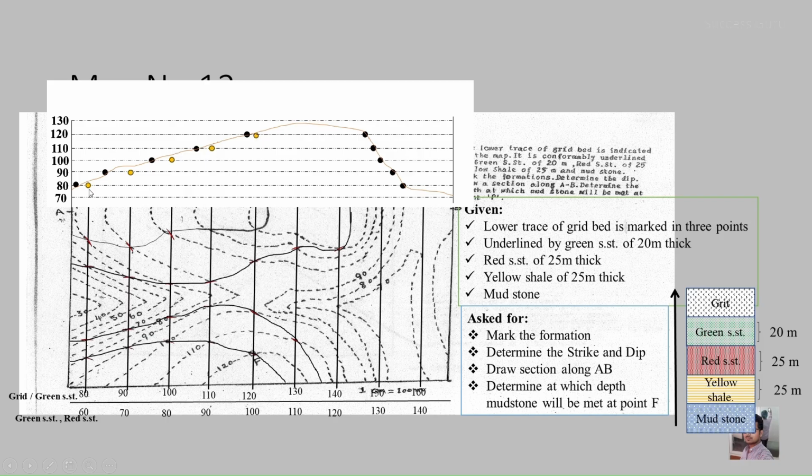So in the previous case what we did is we are just freehand drawing for the profile line, but this case is a bedding plane. It will be a plane, right? So you can use a scale and draw a straight line connecting all the 5 points. And remember, if your points are right, all the points will be lying in a straight line. If you have made any mistake, that is parallelism gone or any other mistake, then this point will not lie in a same line. So here you can see all the points lie in a straight line. So we made it a bit perfect.